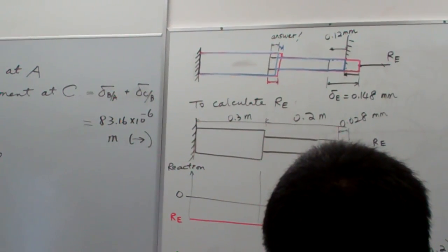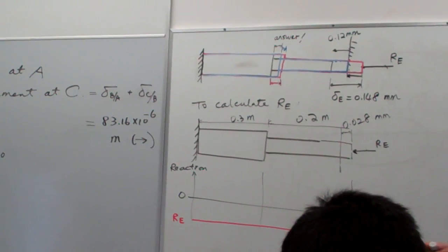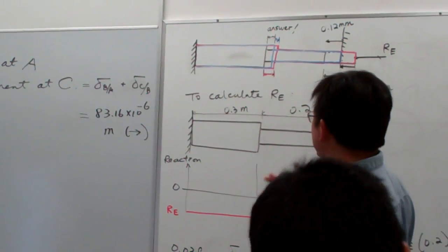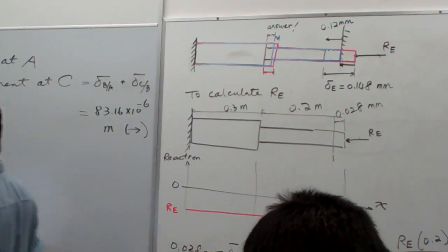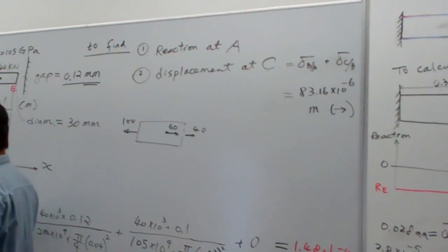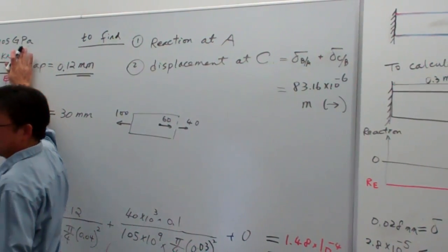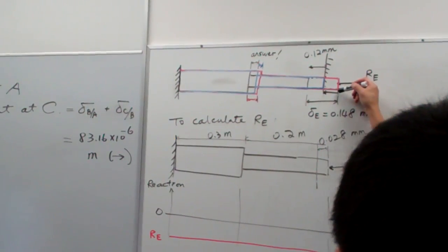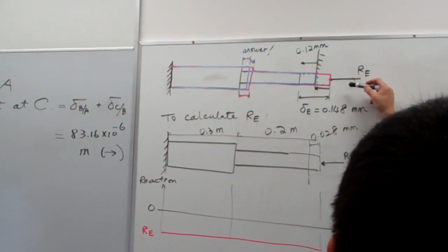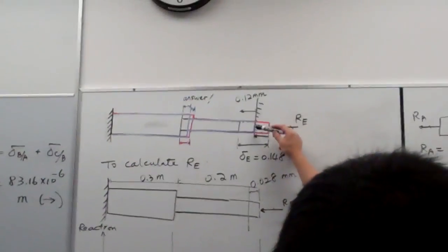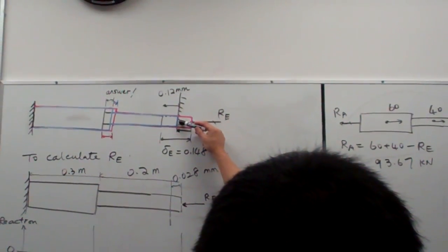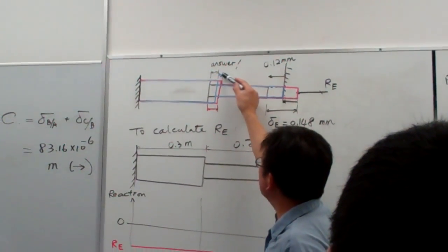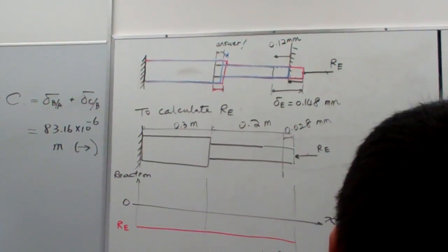Are we okay? So again, here I decompose the problem solution into two subsystems. One subsystem is like this. For this case, we calculate the displacement assuming that it would have no constraint. That is represented by the red color. The second subsystem is due to the influence of the reaction produced at the ground, at the constraint here, that pushes back on the model, and that is described by the blue, which is this one for the first segment.